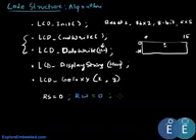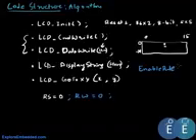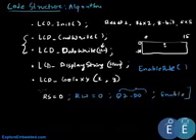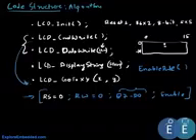Then we have one more function called enable pulse. This sends a pulse which latches the command into the lcd. Before we send an enable pulse, we need to have the command on the data lines. So we keep the command first on D7 to D0, and then we send an enable pulse. This is basically the flow for the lcd command write function.